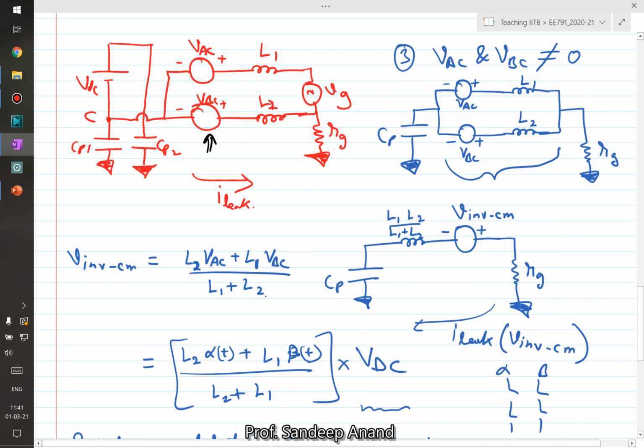Just to give an example, what if there is a transformer in the circuit? You can just include this transformer in this circuit and analyze for common mode current. What if the switches, which are getting turned on and off, form a capacitance with the heat sink? What will happen to the common mode currents now? Again, you go by the same approach, and you can consider those capacitances in the circuit and analyze them also.